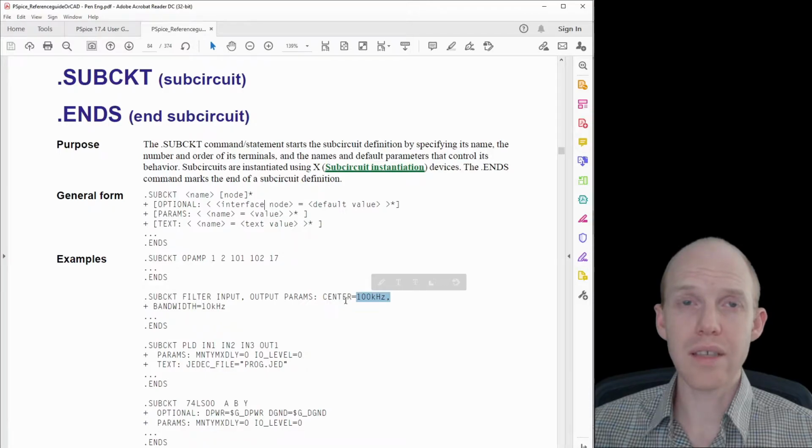And that way, when you're defining these circuits later, you can give it different parameters here. So you can have one template for the part, like the op-amp, and then you can pass in at each definition of it different parameters, so you have custom versions of each one in different places in the circuit.